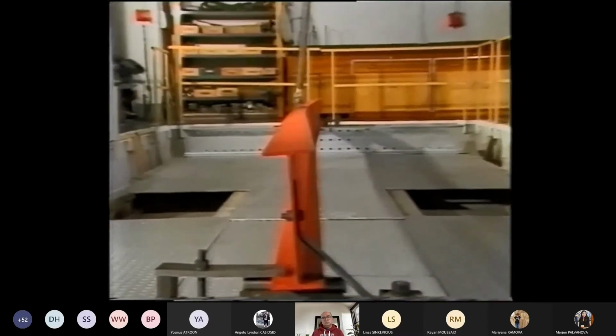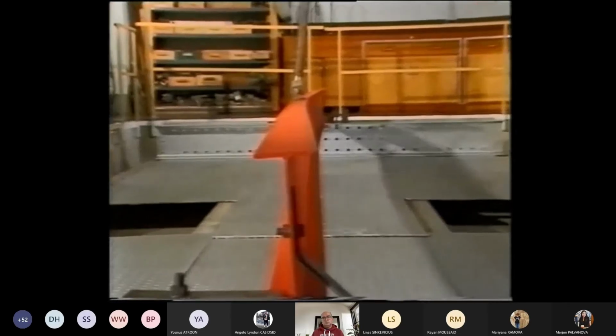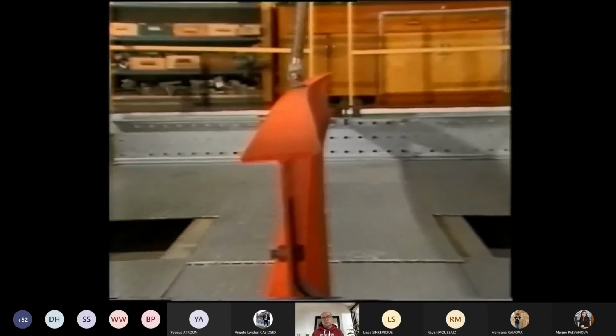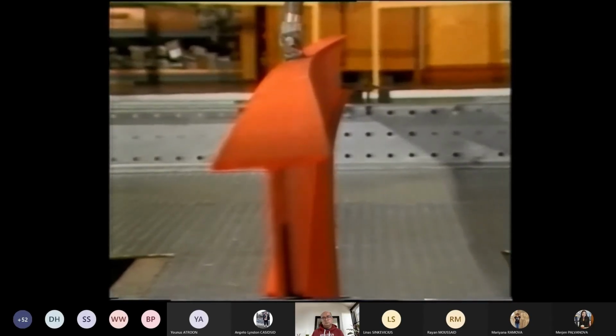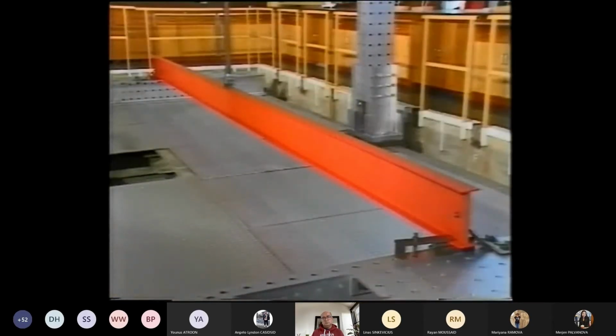This is known as lateral torsional instability. The direction of the lateral movement is determined by the initial imperfections present in the unloaded beam. When the beam is unloaded, full recovery occurs, with the beam returning to its original undistorted shape. No permanent damage has been done to the beam, which demonstrates that the failure is elastic in nature and is due to instability.